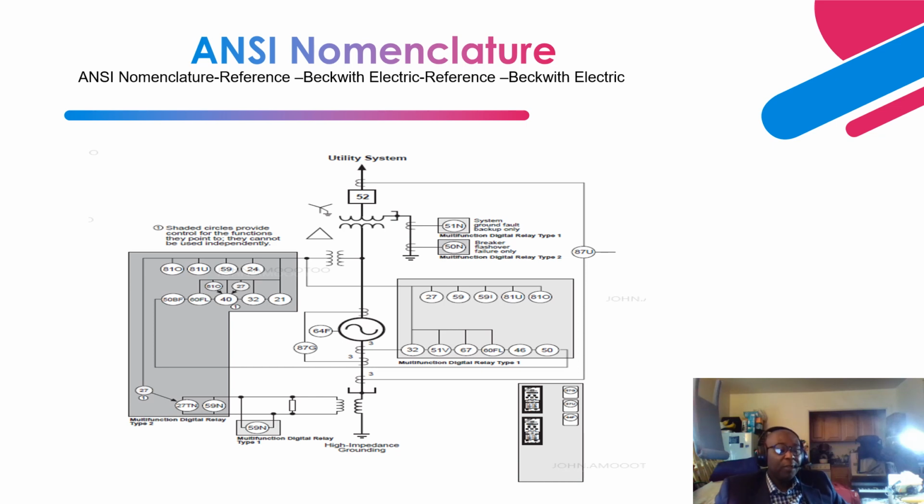Next is 60FL, and that is fuse loss. What it's doing is monitoring the fuse that is connected on the high side of the VT, located at the terminal of the generator. When the fuse goes out, it detects the unbalance of voltage measurements.